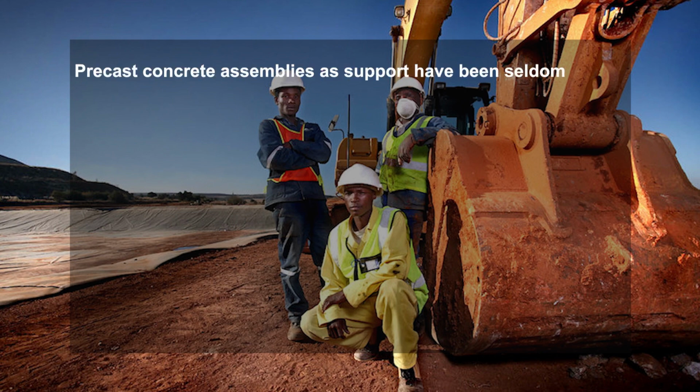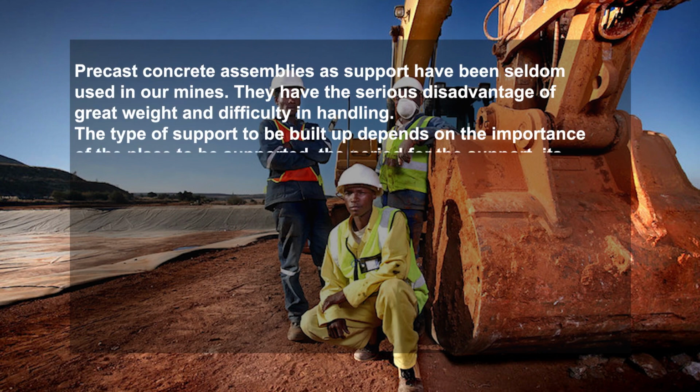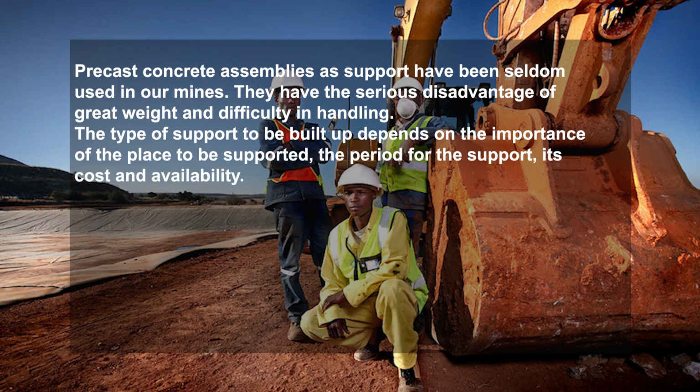Precast concrete assemblies as support have seldom been used in our mines. They have the serious disadvantage of great weight and difficulty in handling. The type of support to be built up depends on the importance of the place to be supported, the period for support, cost and availability.